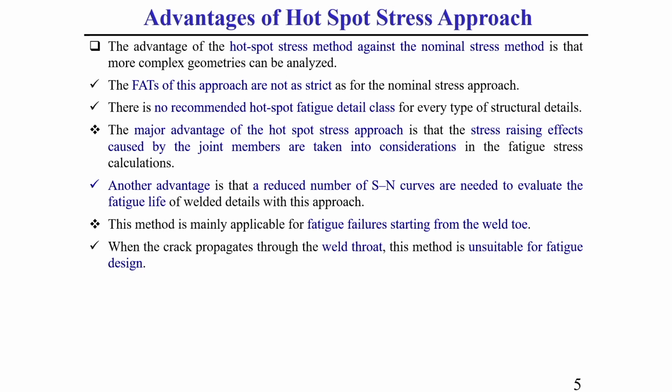And the fatigue strength values of this approach are not as strict as the nominal stress approach. This is also another advantage of the hotspot approach. How it is, I will discuss in detail in a subsequent slide.